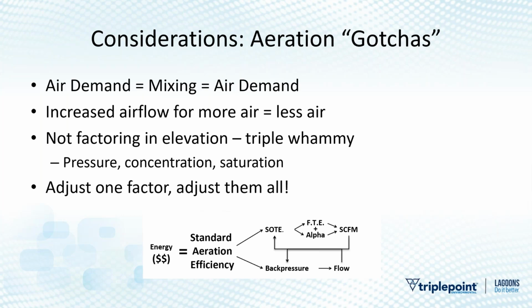Well, we're not just putting in air, we're putting in mixing too. And when we add mixing, we can get to the point where the air demand creates the mixing that increases the kinetic rate, and then increases the air demand, and it becomes a circular issue where you keep having to chase and put in more air to address the demand you're creating with that air. So keep an eye on that. We've gotten into that pickle a couple times.